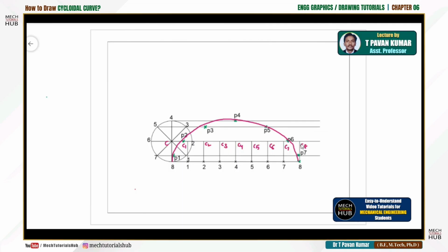Now when you place the compass on C8 center with a radius of 25, if you cut, it should come and touch this particular 8th end point division. Alright, okay. Always C1 as center, 25 as radius. C2 as center, again 25 mm as radius. Till 8, 25 mm as radius. You are going to get the intersections, accordingly join them all. This is how the practice will go.